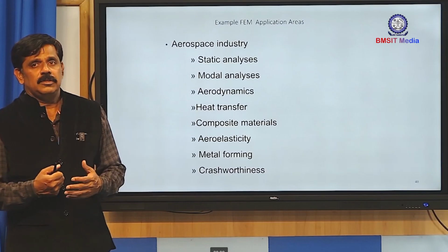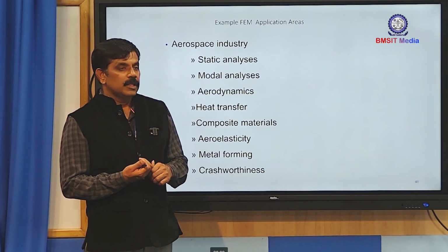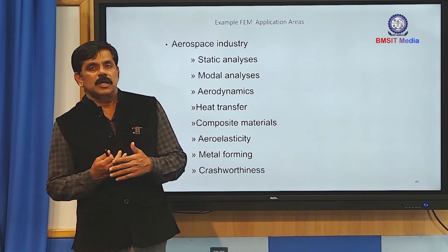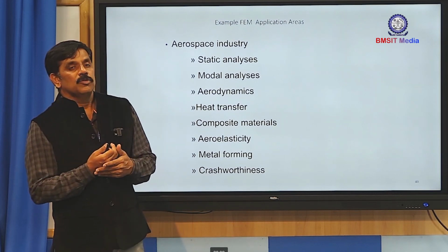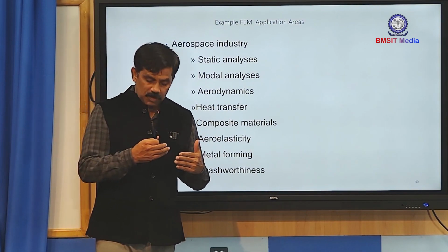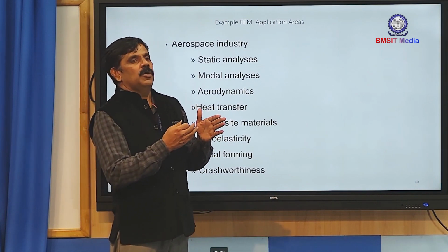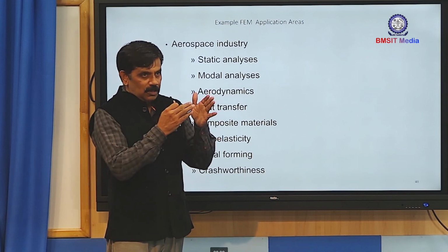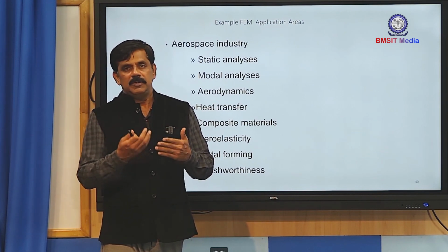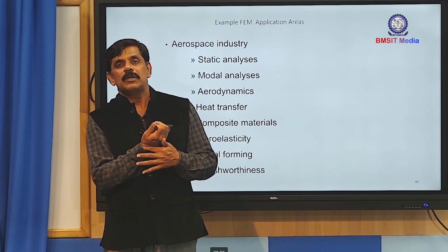So today we have discussed the different types of analysis, especially engineering analysis. For an engineering problem, we can get a practical solution, which is one option, and an analytical solution is one more option. When a practical as well as an analytical solution is not possible or feasible, in such cases you have to go for numerical analysis or approximate analysis. The finite element analysis is one of the numerical or approximate analyses. So we have discussed different applications of finite element analysis from the automotive industry to the aerospace industries. Then the concepts and different stages in finite element analysis. From the finite element analysis, we get the displacement. From the displacement, we get the strain. From the strain, we get the stresses induced in the body. From the induced stresses, we can compare whether our design is safe or not.